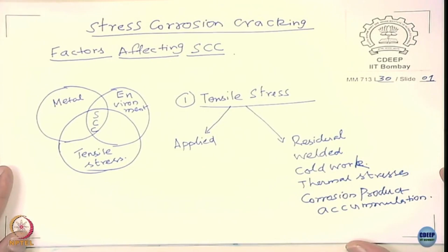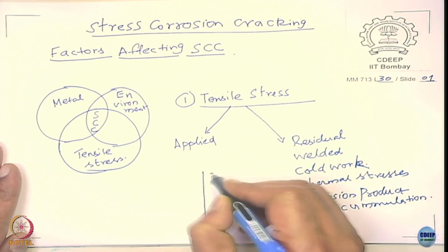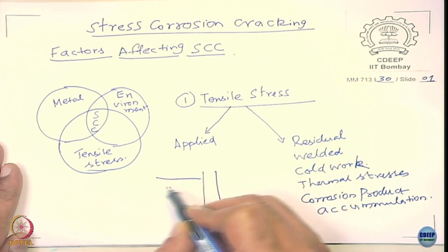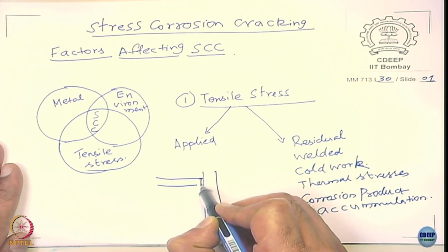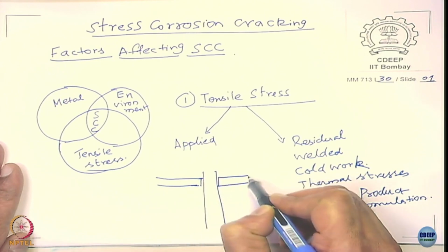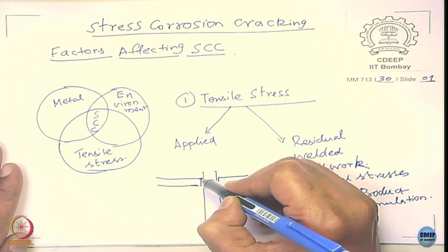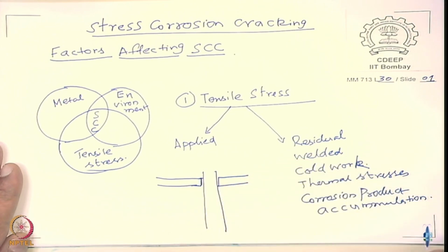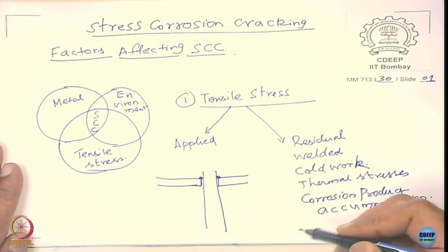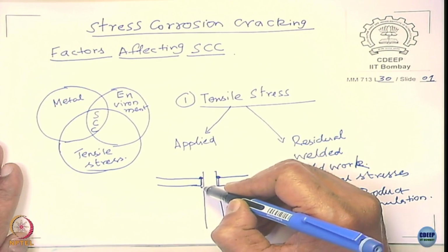I give an illustration. You guys have some exposure to heat exchangers, right. In a heat exchanger, you would have a tube and a tube sheet. You weld it, or sometimes it is an expansion joint, mostly it is an expansion joint, right. You expand it, and sometimes you weld on one side, normally where it is facing outside they weld it, and this side is not welded, right.